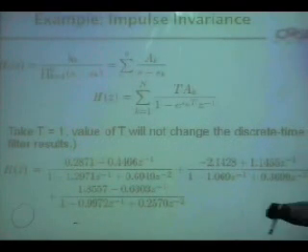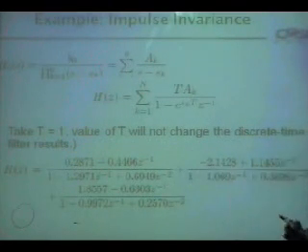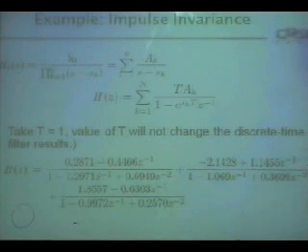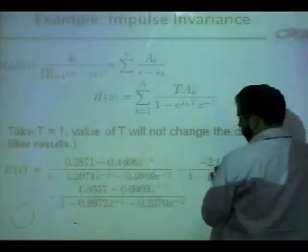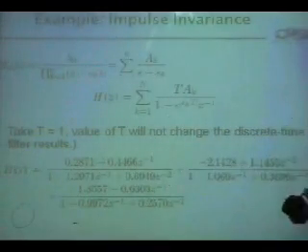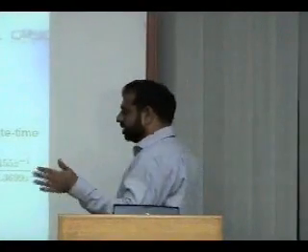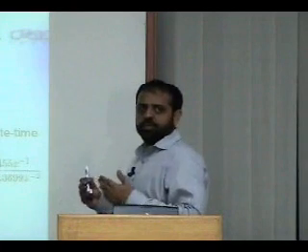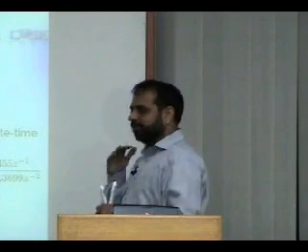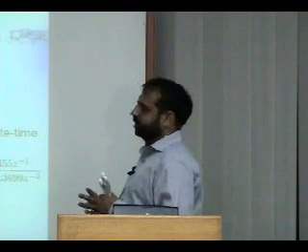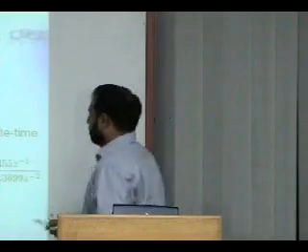We usually prefer second degree polynomials, because then you don't have to deal with complex numbers. And remember, a second degree polynomial is a difference equation, so this is as if you are implementing three of them in parallel. Three second order systems in parallel will make a sixth order system. It's up to you. You can just implement one long difference equation, but it is usually preferred to break it down into second order sections. That's what MATLAB does for you. It always gives you second order sections, so second order sections are better.